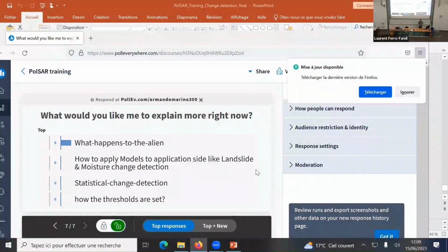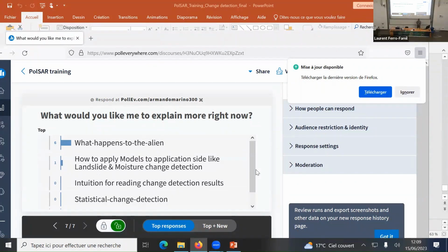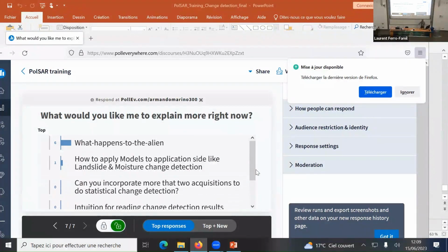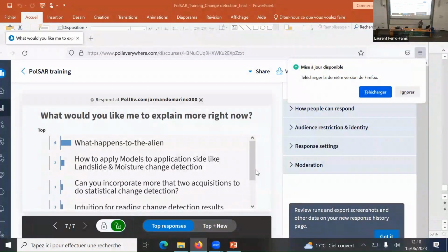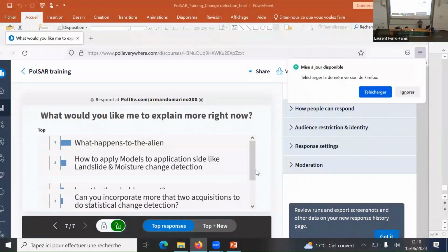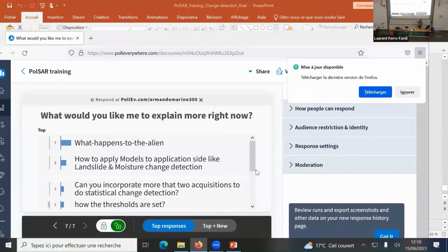It generally is consistency. It depends on which type of detector you're using. If you take just a channel and then you do a threshold on that, then the only thing you really need to do is consistency. If you go linear, they will have some distribution, say a Rayleigh or whatever, or exponential if it's your intensity. If it's the log one, they will have a log-normal distribution, normal distribution, or something different.